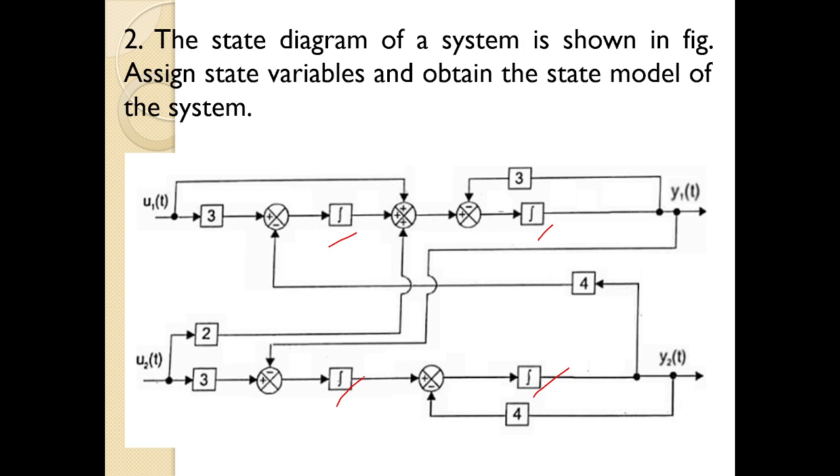These state variables can be assigned at the output terminals of your integrators. What is the input? These are the input sides of the integrators. What is the output? This is the output. So you can write the state variables at the output side of your integrator.